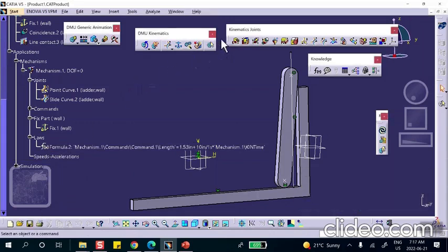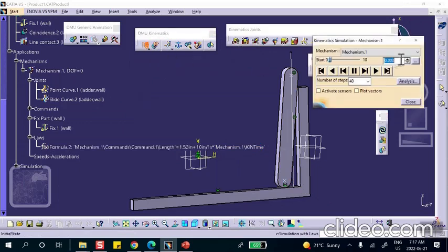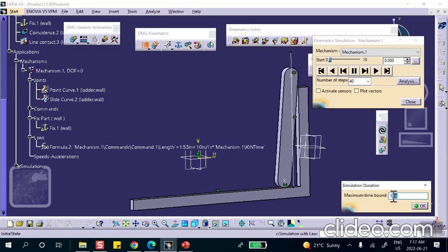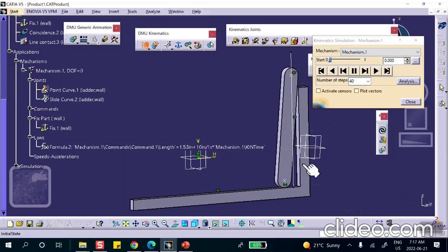All right, so we're going to do simulation with laws, and then later on we're going to put a sensor here and plot the velocity and stuff like that. Now, default is 10 seconds. So 10 seconds times 10 inches per second, that's going to be 100. That's a lot of distance that's going to travel, which it won't, obviously. So let's make it 1. That's going to be a maximum of 10 inches.